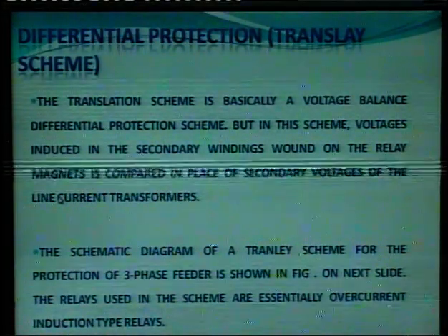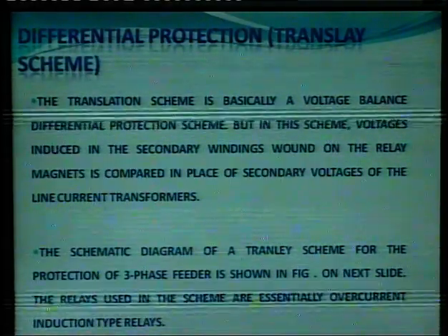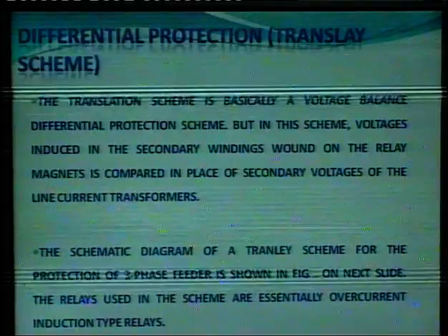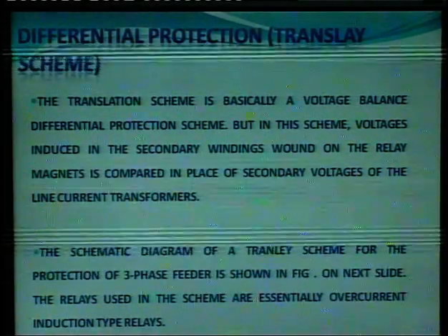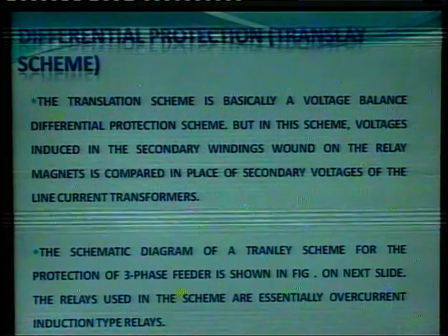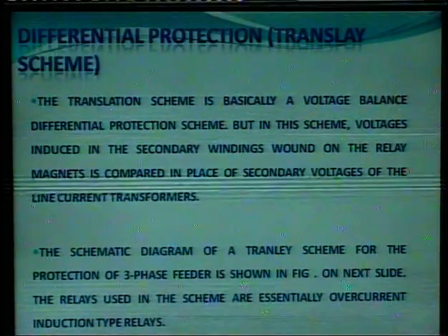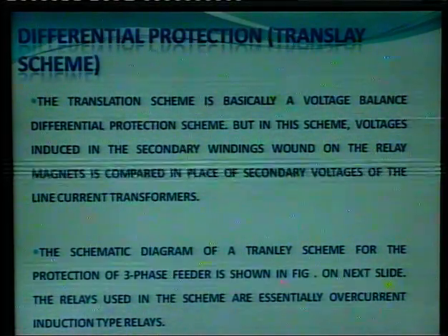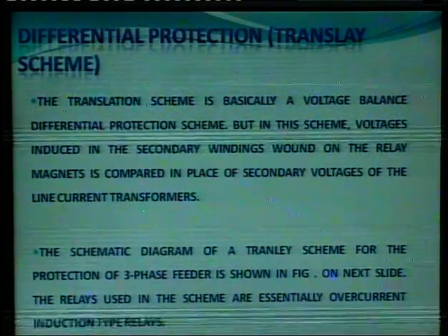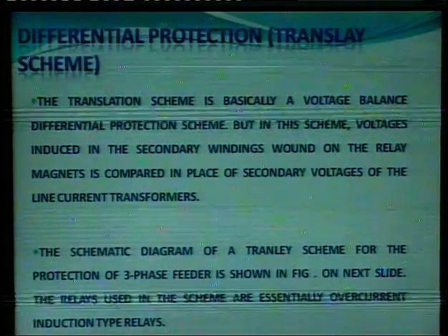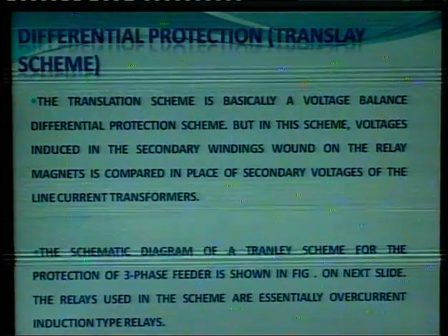Now the next scheme is the differential protection of feeder. It is also known as the Translay scheme. The Translay scheme is basically a voltage balance differential protection scheme, but in this scheme the voltages induced in the secondary windings wound on the relay magnets are compared in place of the secondary voltages of the line current transformers.